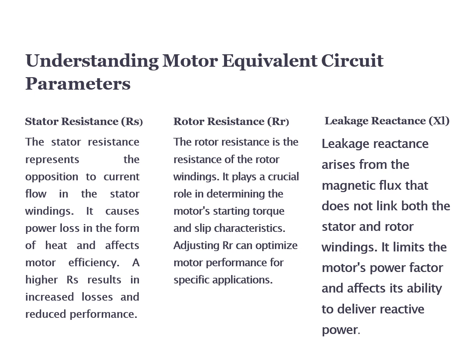This arises from the magnetic flux that does not link both the stator and rotor windings. It limits the motor's power factor and affects its ability to deliver reactive power. Managing XL is essential for improving the motor's overall efficiency and power delivery.